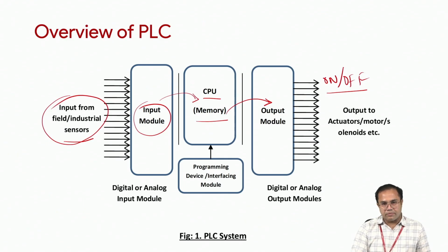So like this, the operation will go on continuously, because in the PLC a program cycle goes on. In the program cycle, it continuously performs the input scan. With the help of the input scan, it gets updated with the input status. Whatever changes occurred across the input will get updated in the input scan, and then it will perform the program scan, so that the program scan will refresh, or take the decision based upon the input status.